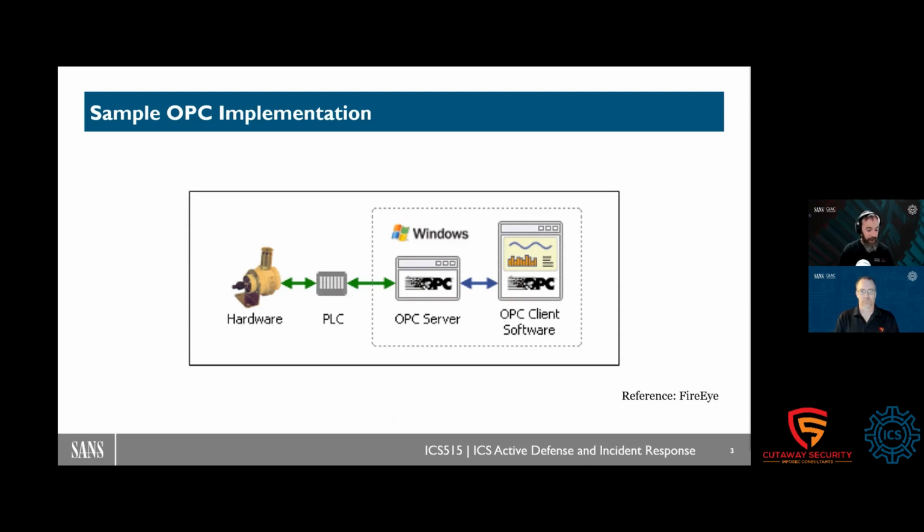You see on the slide there where we talk about the OPC server and client applications. In this implementation, we've got the server and the client sitting on the same box. And again, OPC Classic is using a Microsoft COM protocol. One of the reasons that OPC UA came out was that heavy reliance on COM and DCOM, where we do see this split across 2 different areas.